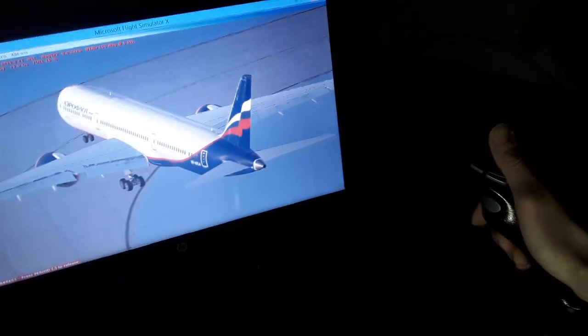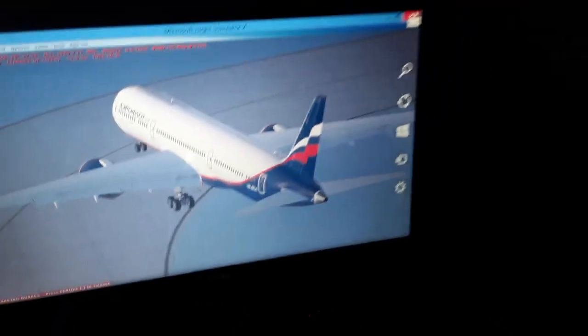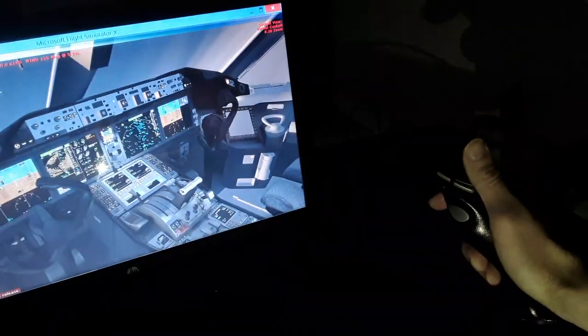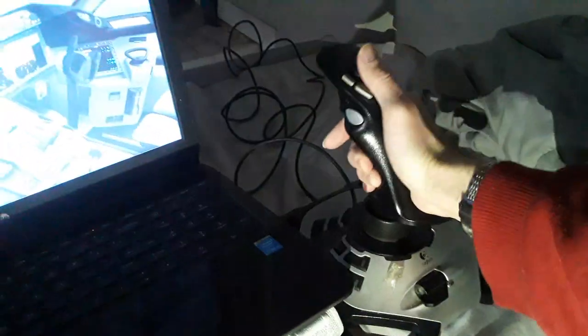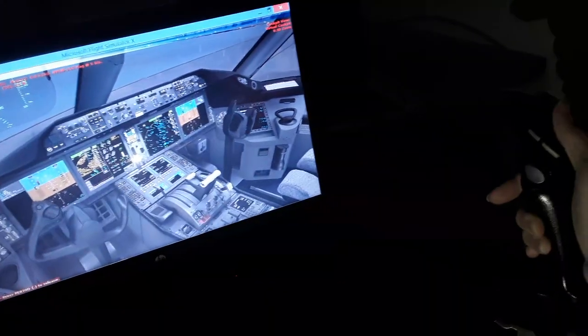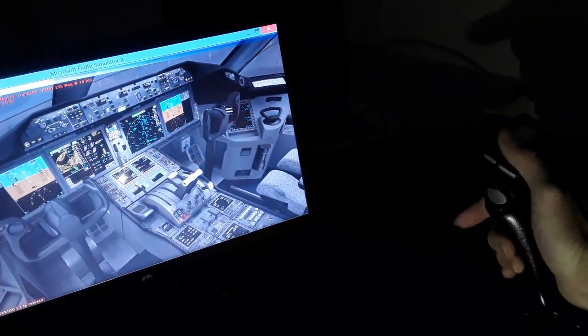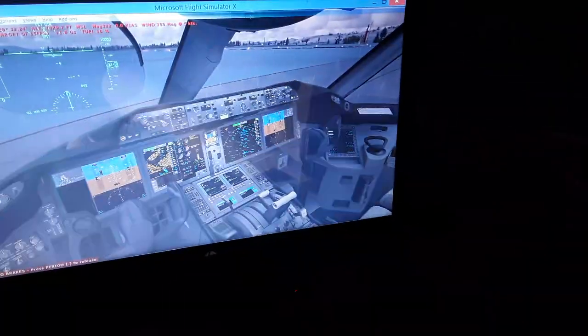So in the Airbus, aileron, spoilers, side stick left and right. Like this, you make a differential lift from the left and the right wing, and you make turns left and right in the air. So it's quite easy to remember. It's the control wheel left and right in the Boeing aircraft. We have the control wheel left and right turns. In the Boeing it is the same, like side stick left and right in the Airbus, also climb, descend, back and forth. Airbus, Boeing, same flight controls, no difference. Rudder pedals also, directional control, rudder and nose wheel steering.